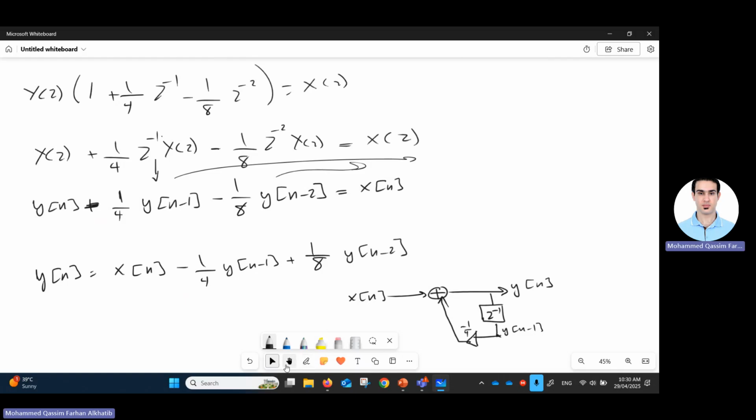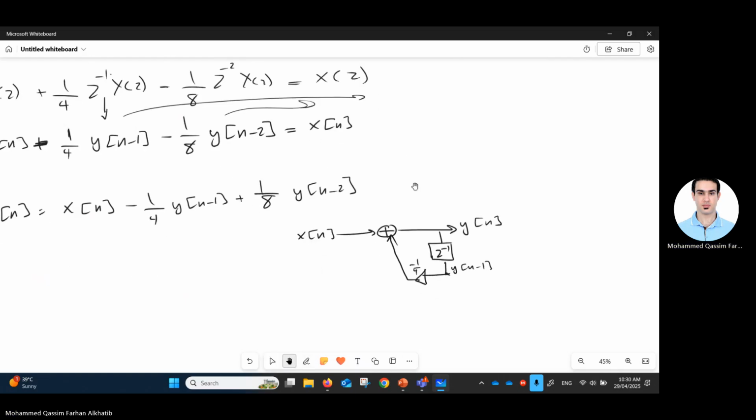Now there is another delay because I have another delayed version here. Now notice here, I have y of n minus 1, z negative 1, that's a delay by an extra unit. So you don't have to do z negative 2. You cannot do that. It's only a single delay unit. So I have the first delay unit, got y of n minus 1, delay it one more time.